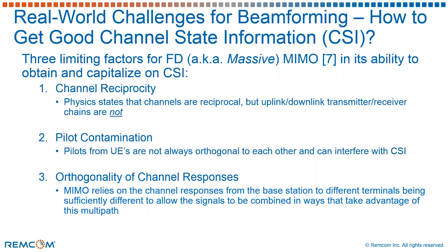And the third is what's known as the orthogonality of channel responses. MIMO in particular relies on the channel responses from the base station antennas to different terminals being sufficiently different that it can apply MIMO techniques to improve the channel or to do things like beamforming.